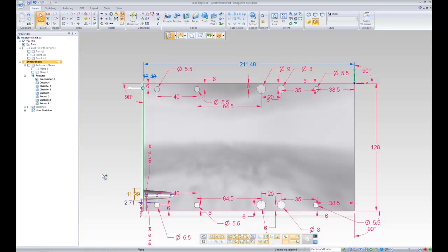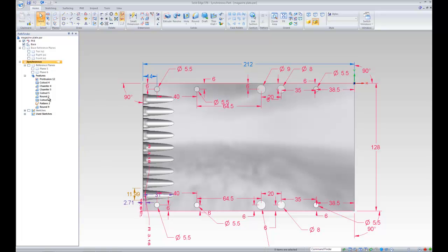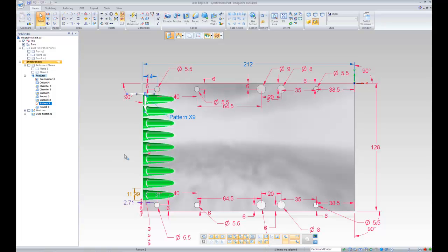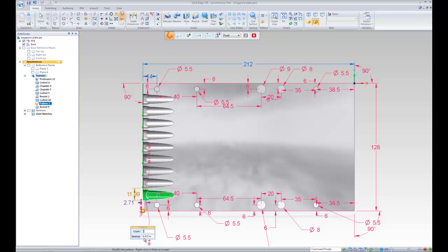You'll notice the pattern disappears. This happens a lot of times with patterns. So the answer is you can step back and you can click on the pattern. If you don't want to be bothered to measure center to center, you look down here and you have your spacing. Write that down and remember it in your count. Let's back out of this.